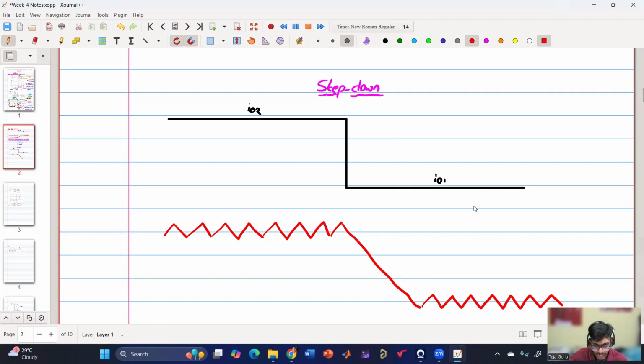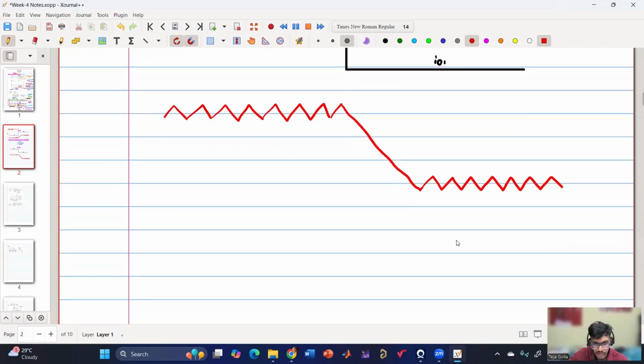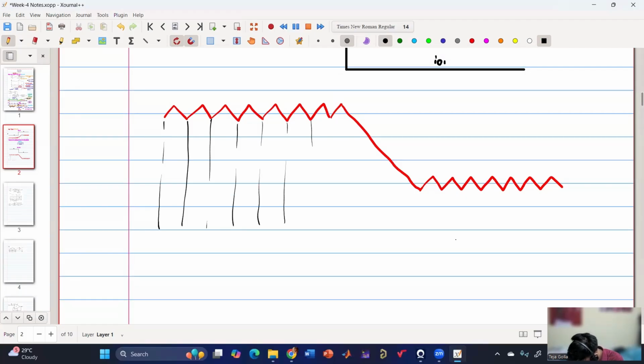So this is like an ideal situation, but in practice there can be transients. But I'm saying that this can be a possibility where it is turned off and then we can get optimal response. So now if we draw the gate pulses for this as well, as the off time is variable, the step down response will be really good for constant on time. So now we have on time, on time, on time, off time.